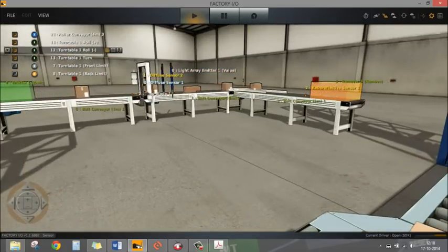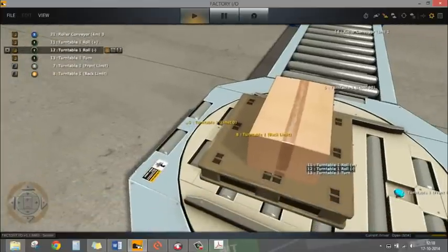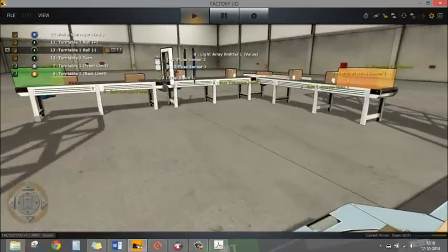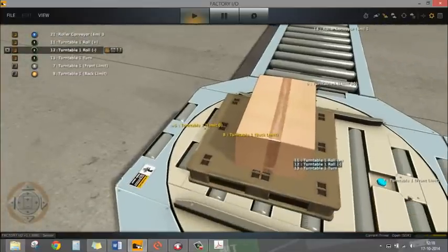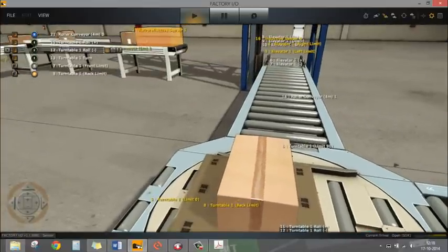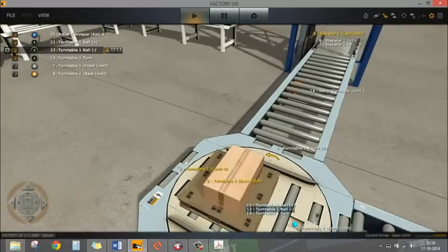Here you can see that the distance is more than capacitive. So a capacitive sensor cannot be used in that application where we have used diffuse. But diffuse can be used here, but it's wasteful to use it here because you don't need that much length, so you may pay a higher cost. So this was how we can use a capacitive sensor.